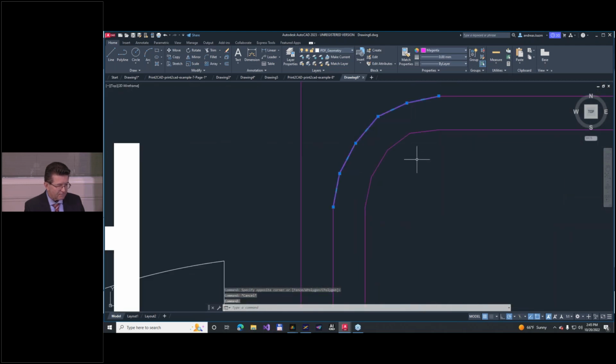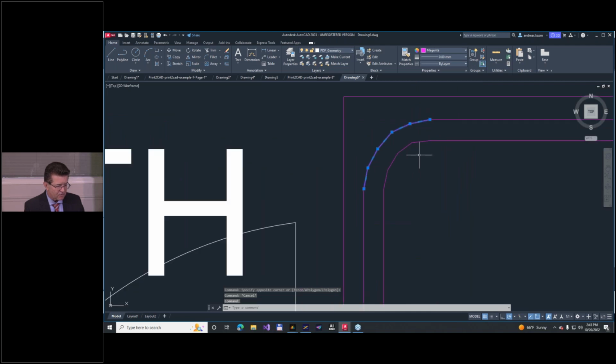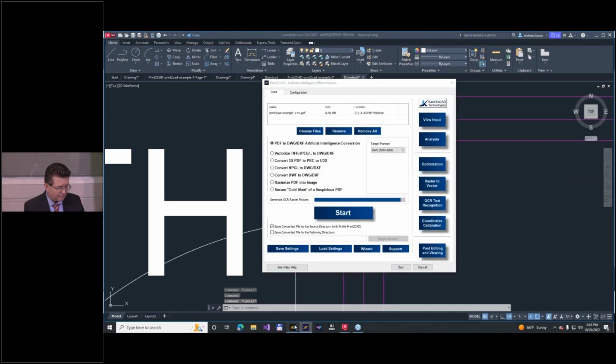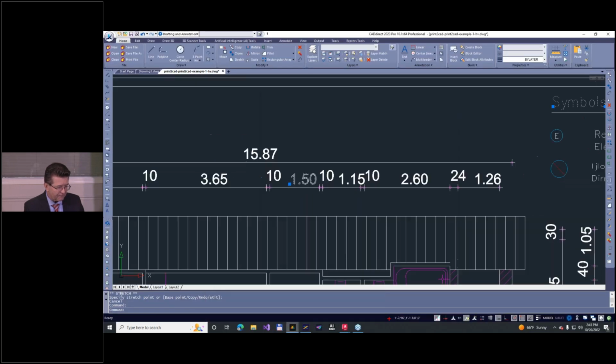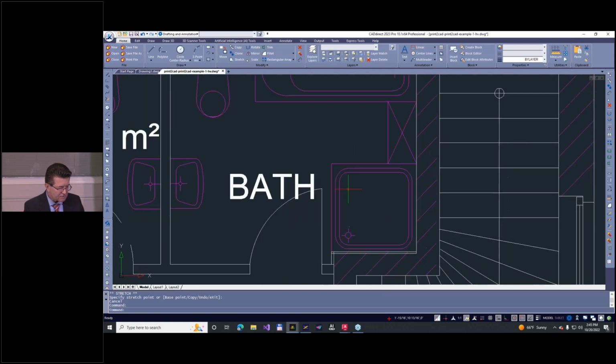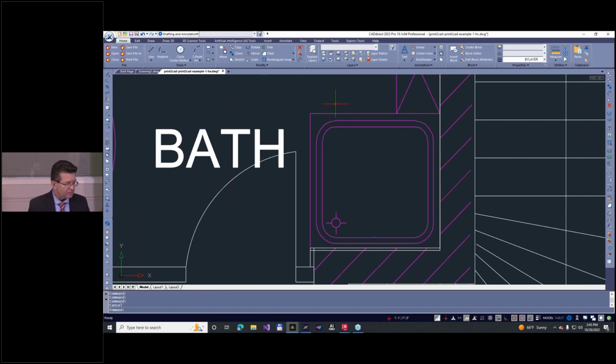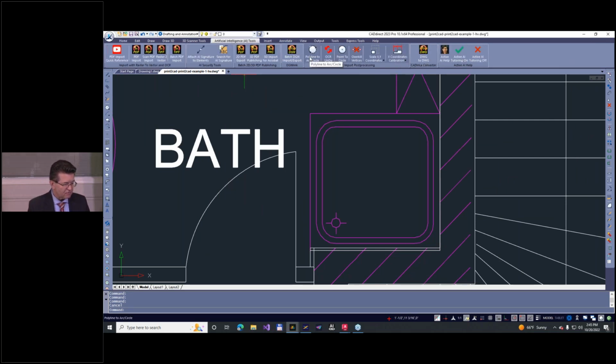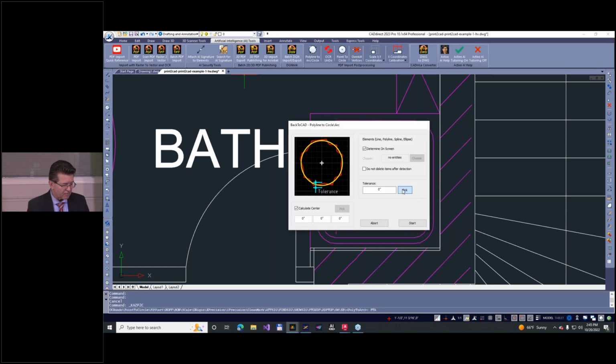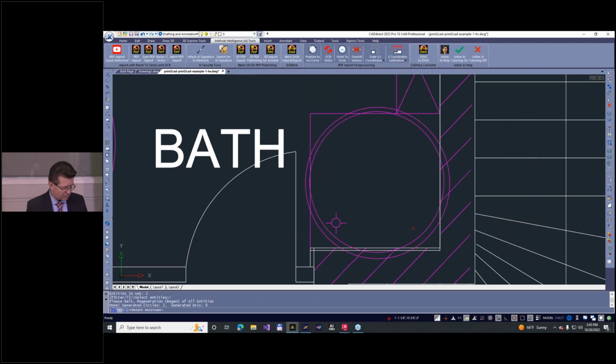This is still not a circle. But in our CAD Direct with Print2CAD, you can go here, okay, on the function and check, oh, I have to correct it. Okay, let me do it. Artificial intelligence recognition of circles and arcs. This is my tolerance, a huge tolerance. Start and like this. Oh, this was it. The tolerance was too huge.